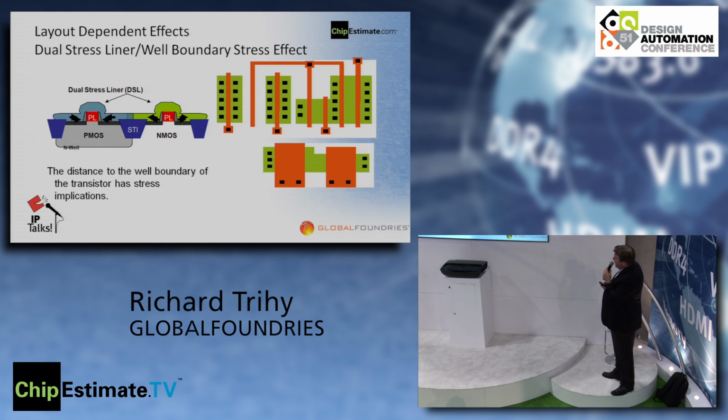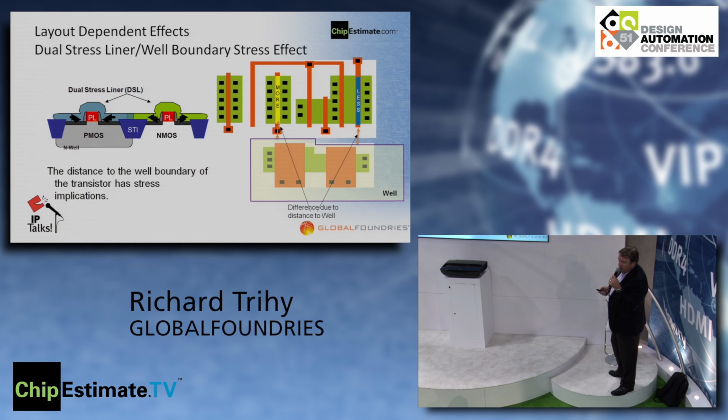We want stress. But designers want to be able to predict it at the schematic level. And one of the challenges we have is that over here, the proximity of the transistor to the N-well boundary has an impact on the amount of stress that you're actually going to see in practice. So in this case, this transistor, because it's further away from the boundary, is going to have less stress than this one, which is close to the boundary.